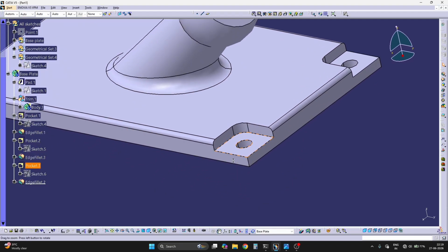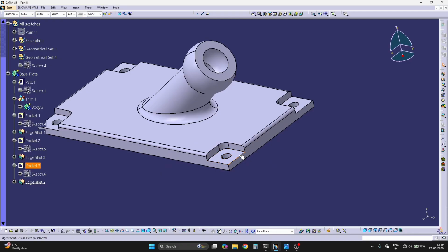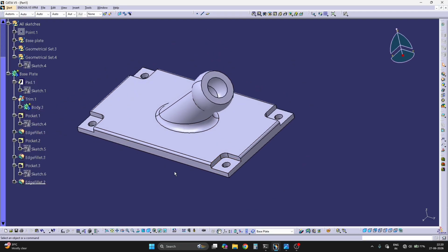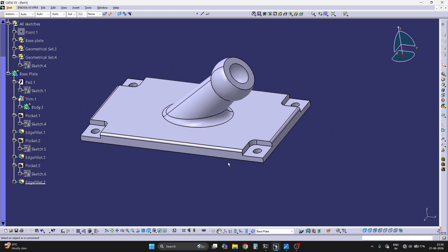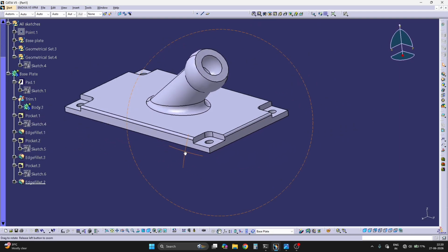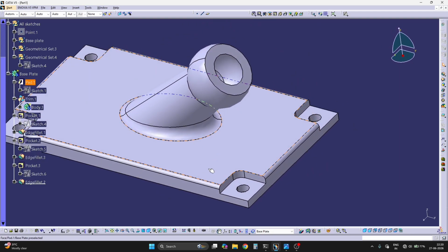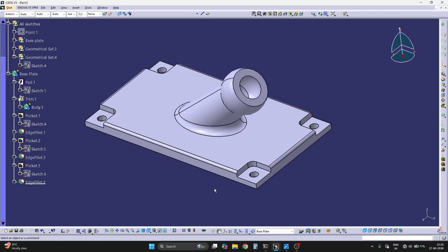What is recommended is to make the feature as a 3D model, not as a pocket. We'll have to make it as an extrusion, then subtract it from the main body, like the boolean operation we did here. Anyway, this is the easiest and most understandable way to model this part.